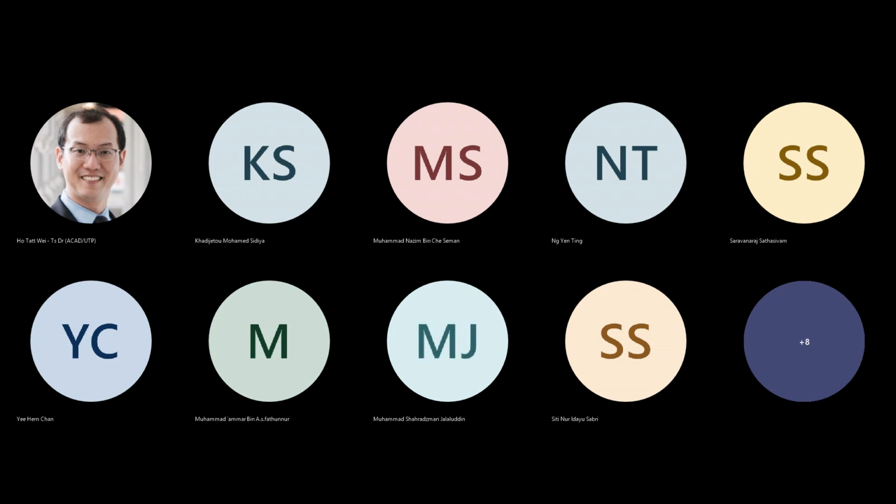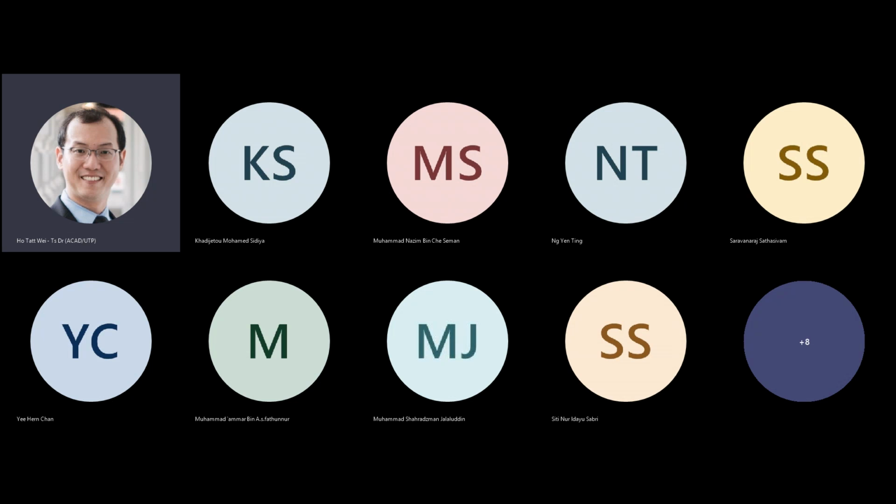Right. So we start with the silicon wafer. It's a flat piece of, well, silicon is literally derived from sand, and it's polished and in a lattice structure, polished to be a really, really flat piece. That's why it looks reflective like a mirror. And what happens is, in this silicon, there will be certain atoms that are implanted in them. The reason you implant them is because you want free electrons floating around, or free holes if this is a p-type, right?